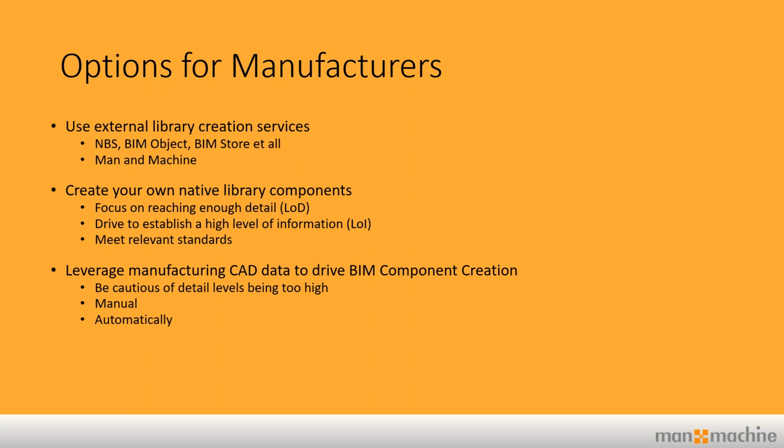The next thing you can do is actually leverage what you've already got. So again, I'm guessing that the majority of people on the call as manufacturers will have some form of parametric CAD software. Now, we're an Autodesk house, so I'm going to be biased and say that Inventor is fantastic. It actually works really well with being able to leverage your manufacturing CAD data to drive your BIM component creation. Other manufacturing CAD software advertises that it can do such thing, but it advertises and pushes it through things like IFC. You should not be using IFC to drive a BIM object.